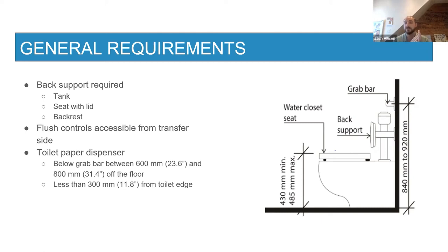And that's going to have a different depth, like I mentioned, from the finished wall to the backrest itself and to the curve of the grab bar supporting it, to make sure that it goes around and fits in snugly with the flush valve. If you push too far out, then you end up with a conflict with the toilet seat and it can't go a full 90. So that's the purpose behind those two different models. If there is more definition in the code in the future, then we'll certainly bring that up.